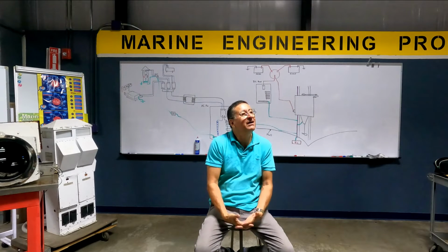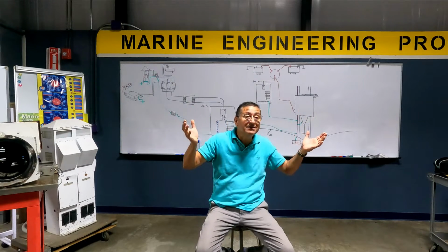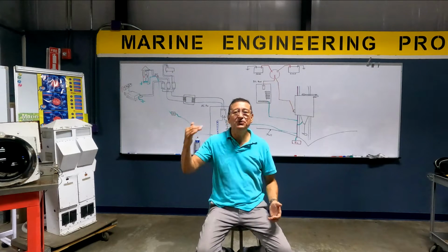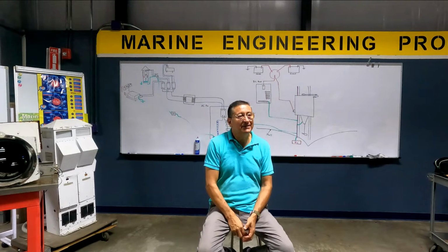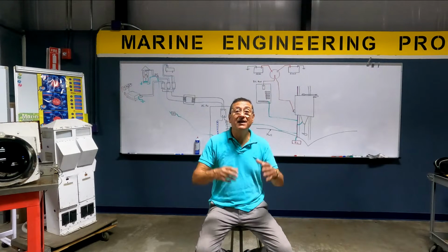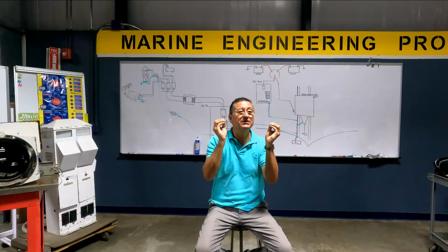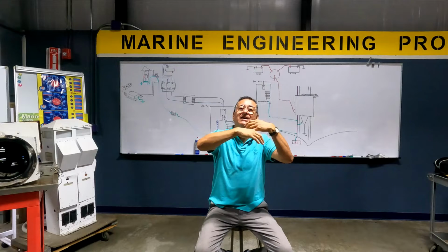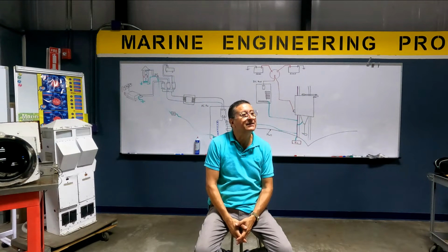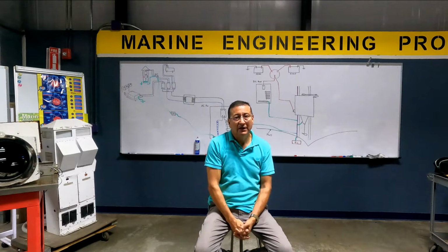No, because number one, you don't have a lot of appliances, and because you don't have AC current in the boat. When you introduce AC current in the boat, your problems start because you need to think how you are going to drain all of those static electricities accumulated in any metals in the boat. Is that situation clear? For that reason, the bonding is necessary, it's mandatory.